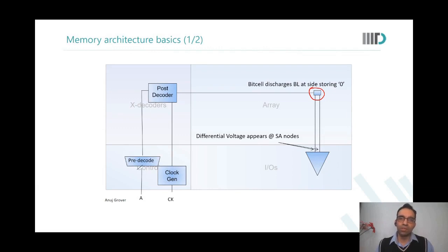We talk about ROMs being very, very dense, DRAMs very, very dense, flash very, very dense. So for that purpose, we do not go for differential bit lines there. But when you select a memory cell, some bit line would discharge. And that discharge you will measure, you will estimate, and you will observe at what is called a sense amplifier.